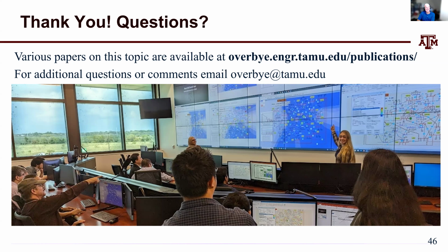He's a former student. In the stability realm, what's going to happen is you're going to start out at a stable equilibrium point. If you don't start at a stable equilibrium point, when you initialize your stability run and give it an initial perturbation, it's going to go off somewhere else. So you start from a stable equilibrium point, and then you give it a kick. It's sort of like taking the ball in the well analogy and giving that ball a kick. And if the kick is large enough, it's going to exit the well. Chances are it will not go through an unstable equilibrium point. So you will not see an unstable equilibrium point. You just won't end up there.